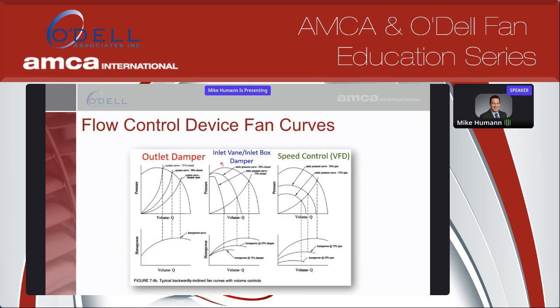You get more flexibility with an inlet vane or inlet box damper. Here's our standard curve where the damper is completely open. As you start to close it off, you start creating new fan curves, and you can see how the volume falls off, but your horsepower also falls off as well. So you're getting horsepower savings here. That may help in certain situations when you don't require as much out of the fan. This gives you a lot of ability to turn down a fan.